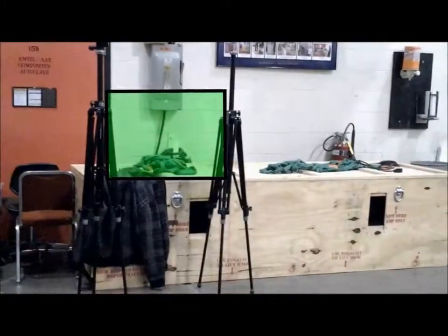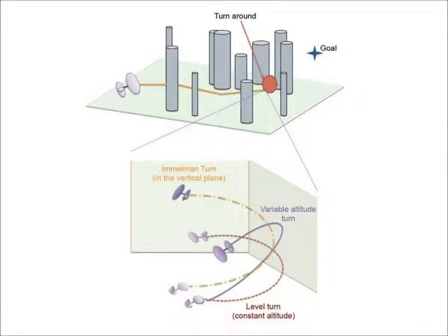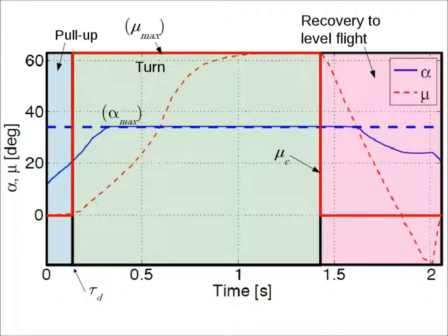In addition to the steady 3D turn, we designed an aggressive turnaround maneuver, or an ATA, to help robotic aircraft backtrack from dense pockets of obstacles. The problem of designing an ATA was posed as an optimal control problem. The numerical solution yielded a three-stage motion primitive.